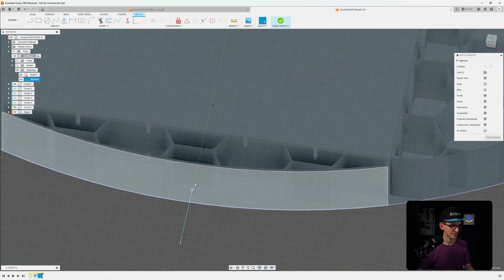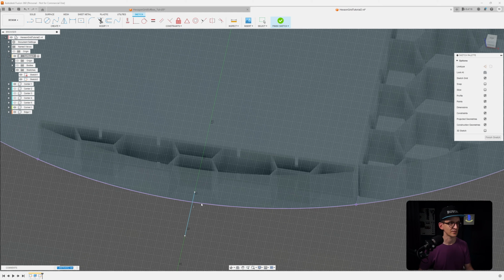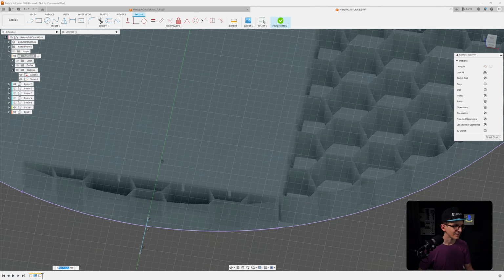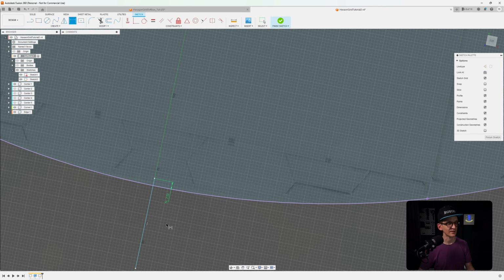Sorry, I wanted to, all right. Select the tangent, so pick circle and arc tangent. Now again, pick circle and arc tangent to be able to reference the tangent instead of from the center point. And we give, why is this down there? What are you doing down there? Okay, whatever. We make sure that this is actually reaching long enough, and that is the outer thickness plus 1 millimeter of leeway so that we are reaching far enough inside.